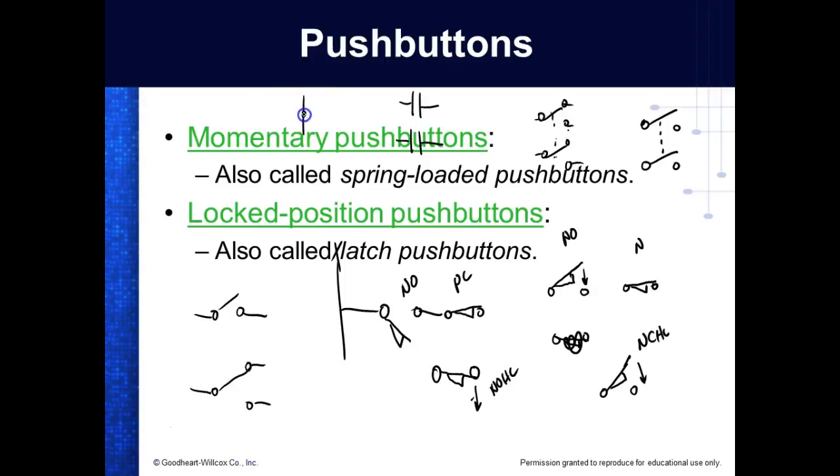We do have some relays that are wired like this. They come over here, and they usually draw them as switches, guys. So that's this guy. It's a control relay. That's this guy right here. You look at the diagram on the side. Right here. So the switches are mechanically connected inside. So this would be a single throw, double throw. This would be 1, 2, 3. That would be 4 pole, double throw. It works just like a switch would, where one of them's open and one of them's closed.